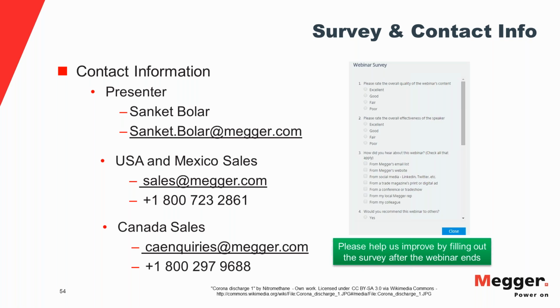Well, per the IEEE 519, when TDD is calculated, you're going to be using either a 15-minute or a 30-minute interval. For each of these intervals, you will measure an average current. And the reference you will use is the maximum average current that was recorded in your test interval. That's the reference to use for the TDD calculation.